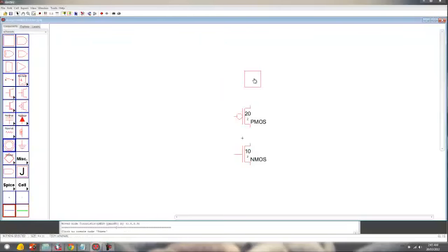Add in a power supply, the circuiting, and press Ctrl B to adjust the size to your liking, and put it there. Add in a ground, Ctrl B to adjust the size. And add one output and input on the left and on the right side of the diagram.